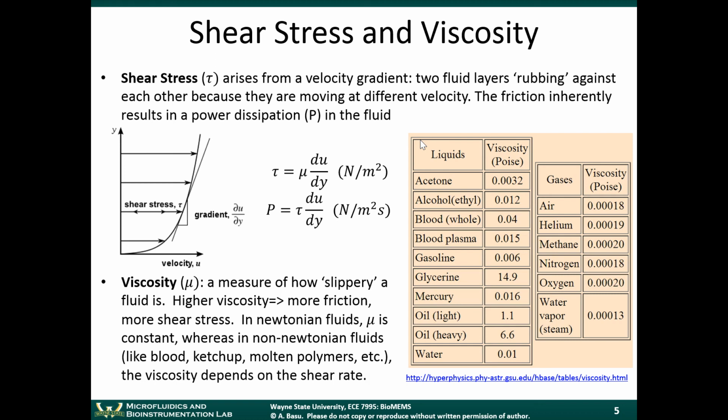If you're dealing with gas flow through a microchannel, then you have compressible flow, because gas can be at high density, it can be at a high pressure or low pressure, right? The equations for compressible flow are a little bit more complicated than incompressible flow. So we'll see the Navier-Stokes equations in a few slides later. But I just want to make sure that we're all on the same page with that. Okay. Liquids, incompressible flow. Gases, compressible flow.